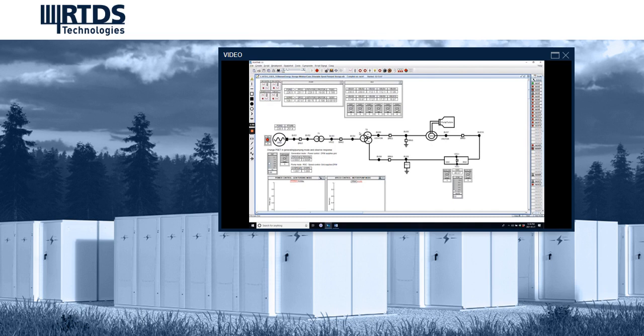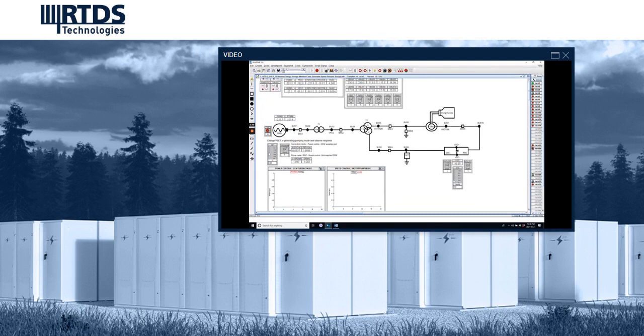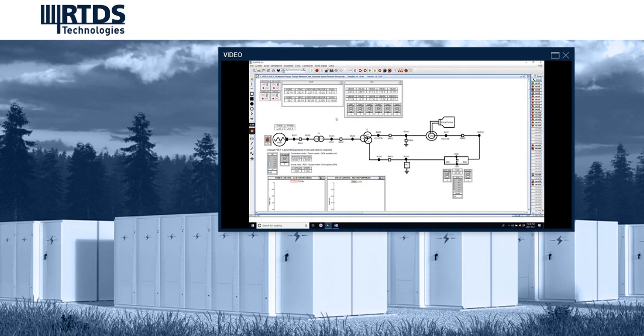In generation mode, the stator power is controlled by the rotor side converter, and the DFIG speed is controlled by the governor, which adjusts the gate position. The power flow in generation mode is from the DFIG turbine to the grid. The step response of the stator power to a step change in the power reference set point when in generation mode will be demonstrated.